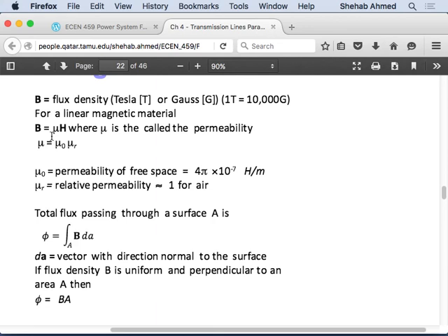And then after you calculate this flux density, you'll be able to calculate flux from there, and then from flux you'll be able to calculate the flux linking the conductor. Outside, flux will be the same as the flux linking the conductor because we only have a single conductor. But inside, the amount of flux will link a portion of the conductor, depending on the ratio of the areas between the conductor itself and the area where the current is flowing, right? And this will be a little bit tricky. Once we go outside, the flux linkage is equal to the flux that you've calculated from this integral here.